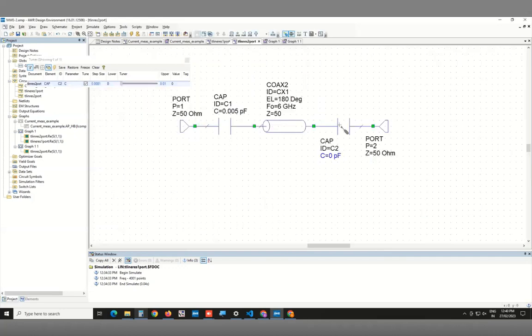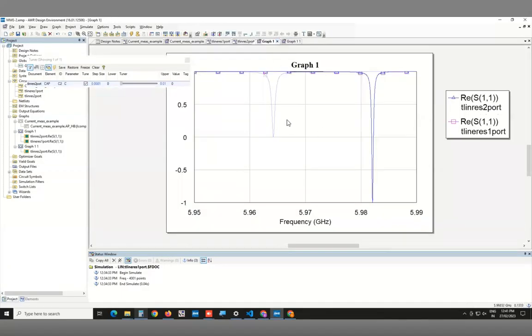Because if I now put this to 0, it's as if this part of the circuit didn't exist as well. And it also means that even though this port is present, this port is not playing any role because it's actually, for all practical purposes, this capacitor is disconnected at this point of time. That's what 0 picofarads capacitor means. Remember, the impedance of a capacitor goes as 1 over omega C. So if C goes to 0, that impedance is infinite. So there's no connection between these two points here. So by reducing this capacitance, you make this match as the single port case.